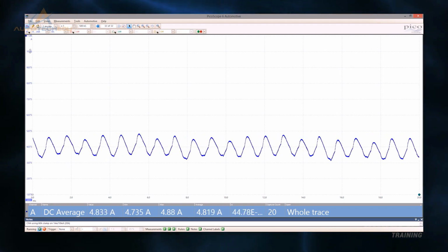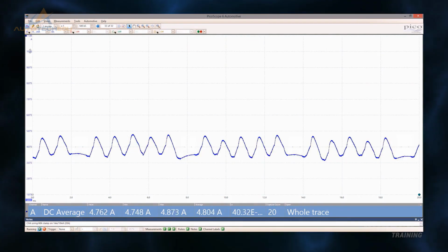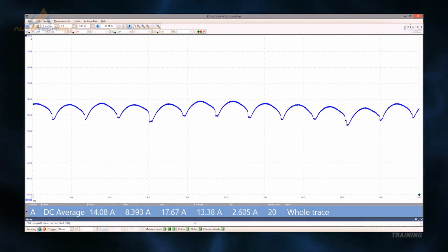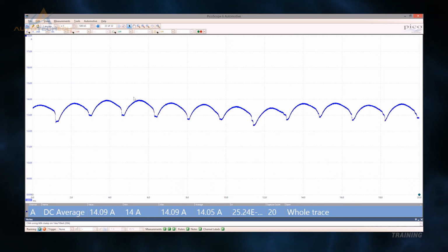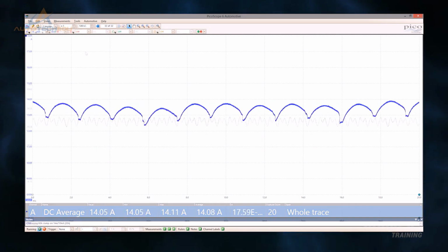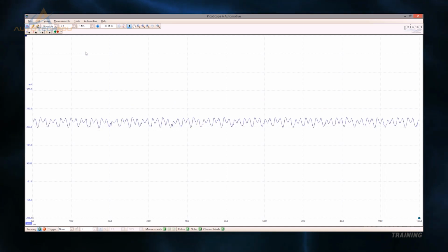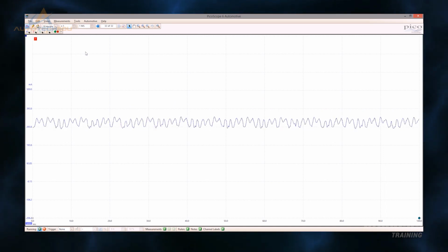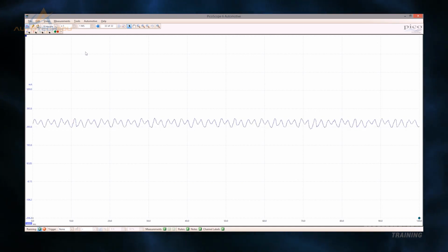Each hump in the trace relates to each sector of the commutator. Any repeated irregularities or disturbance in the trace will signify a fault. A higher than normal current value on the trace will point to a restricted delivery or return line. And again, a lower than normal current draw indicates the pump motor is spinning but with minimal load. This could be an impeller failure, a fault in the pressure regulator, or even a lack of fuel in the tank.